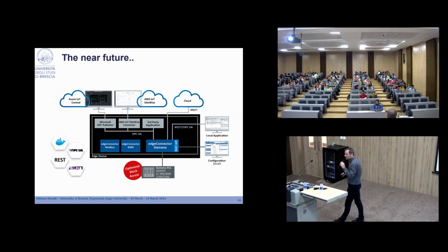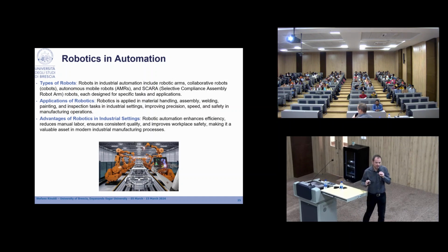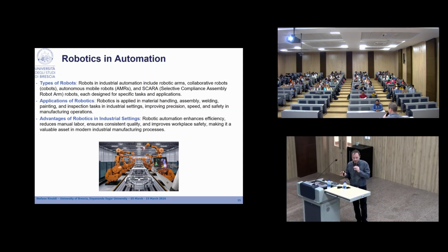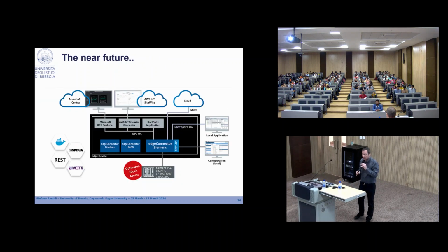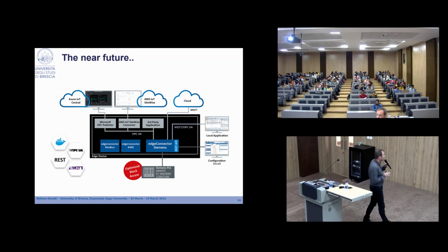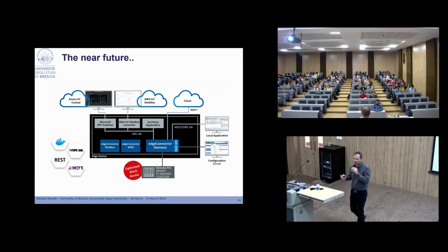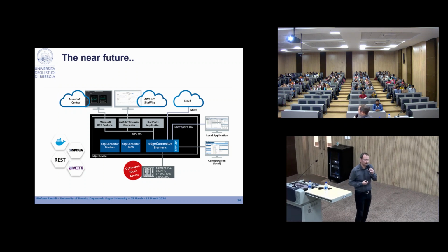The soft PLC, as mentioned before, was just the first step toward the virtualization of the PLC. Nowadays, the current trend in industrial automation is the complete virtualization of the PLC. The idea is to run the PLC software in a container running on an edge computing device.